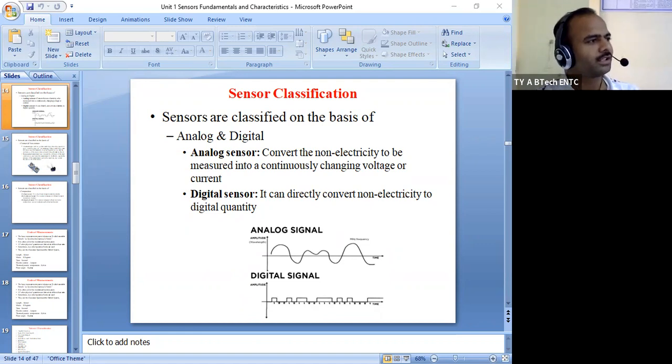You have to press the button and it will open, just like opening the mouth of a crocodile. We have to insert it, suppose this is a wire conductor, and we have to measure the current flowing through that particular wire.